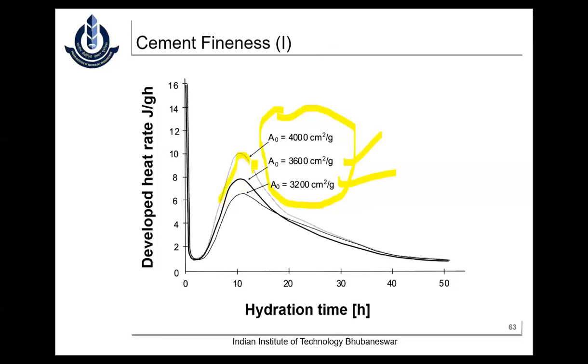In some of the cases I've seen in the blended cements, though in the earlier slides we talked about the rate of heat of hydration being very low, and when it is very low definitely the shrinkage won't be that much. But when you have a very high fineness, no matter whether you use an OPC or a blended cement, the heat of hydration will be slightly more. Because of that, even the blended cements are showing some cracks the next year.